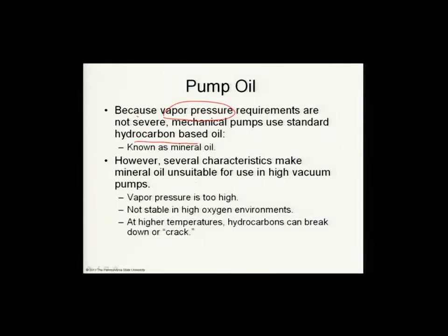If you're using the hydrocarbon oil, known as mineral oil, it can be unsuitable because the vapor pressure can be too high. It can be unstable in oxygen environments. Maybe you're doing some processing where oxygen is present, and so the oxygen can obviously react with the hydrocarbon. And at higher temperatures, the hydrocarbons can break down and crack, that is, decompose into smaller molecules. So you might want to look at not using hydrocarbon-based oil.